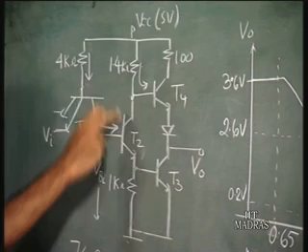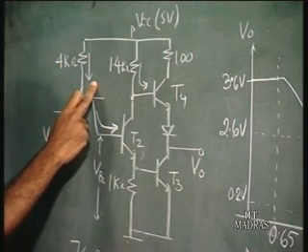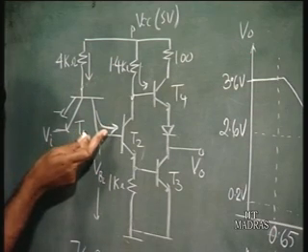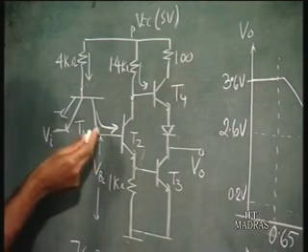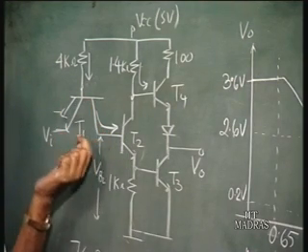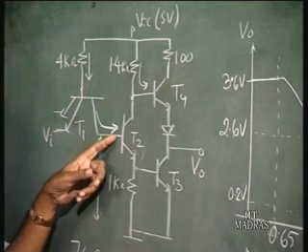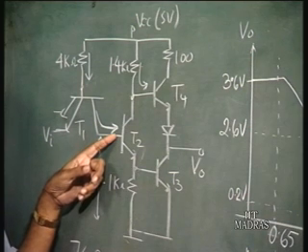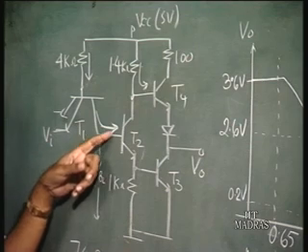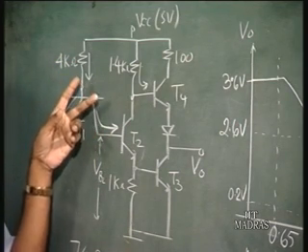So in this T1 transistor, a base current of 0.7 milliampere is flowing, and a collector current, that is a reverse collector current basically, a negative collector current. Normally in a normal NPN transistor, a collector current would flow into the collector. So a very small negative collector current of 56 microamperes is flowing, very much smaller compared to the base current.